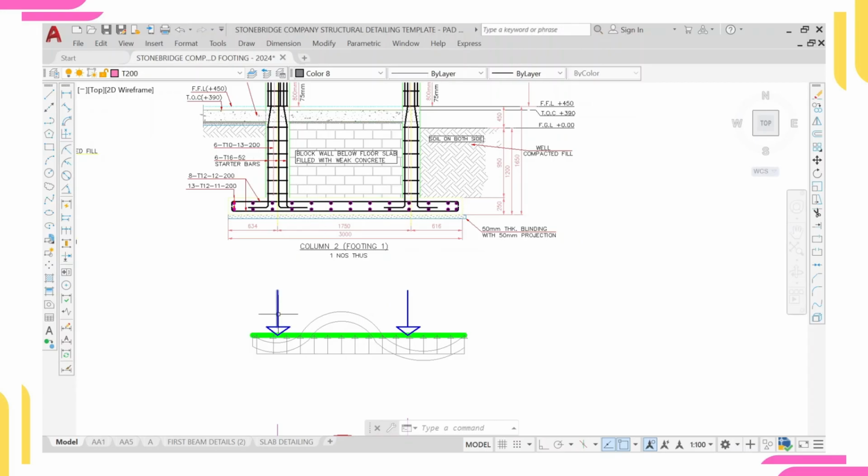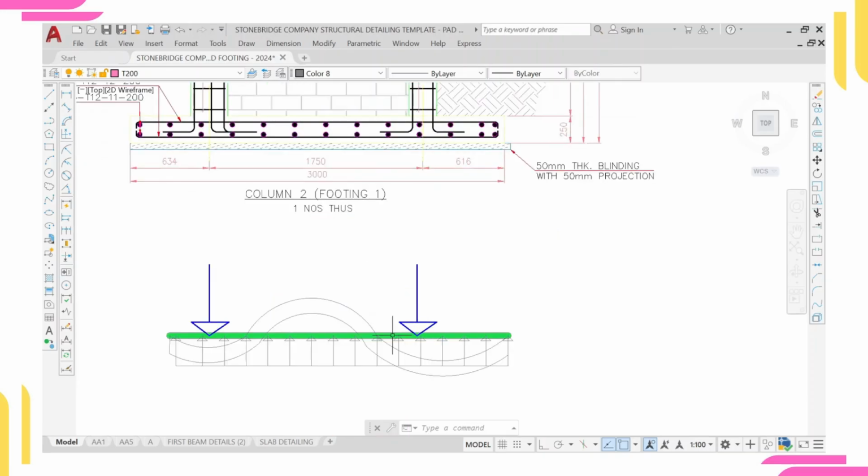And so look at this point load now. This point load means the column. This point load is this column. It is transferring its load to this footing base, which is this one in green color. Then we have this uniform distributed load, which is the soil. It will try to resist the load that this column is transferring to it.